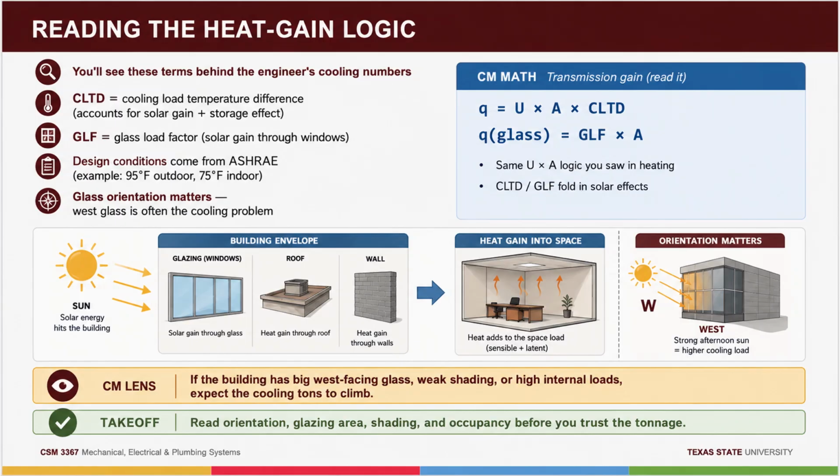Denser, hotter occupancies run heavier. Restaurants and assembly spaces can push down toward 150 to 250 square feet per ton because of the people and the kitchens. Data spaces are in a category of their own. Milder load buildings, warehouses with spot cooling, run far lighter. Quiz alert. Rule of thumb for offices, roughly 300 to 400 SF per ton. Know it, and know its place. Rules of thumb are for conceptual estimates and sanity checks, never for final equipment sizing. Real sizing comes from the load calculation.